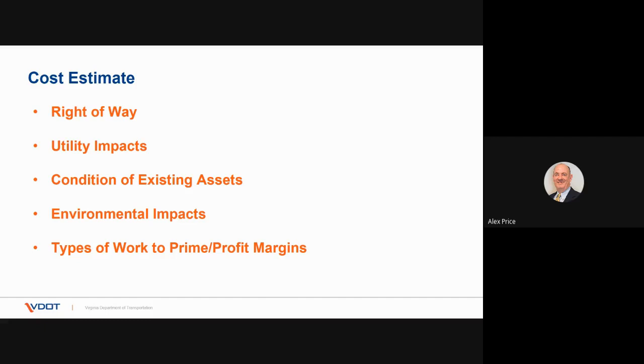Environmental impacts: certainly need to identify potential impacts early on so you can mitigate these issues, eliminating or minimizing the impact. If you can't eliminate or minimize them, at least you can correctly estimate the cost of the impact. This may be in the form of payments for stream credits, payments to a wetland mitigation bank, cost of natural stream design, which is expensive, and may take on the additional cost of the required right-of-way needed to relocate a stream.